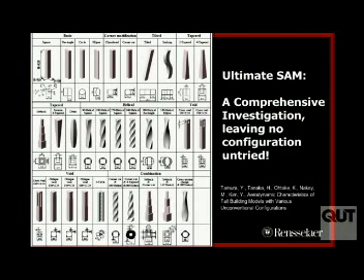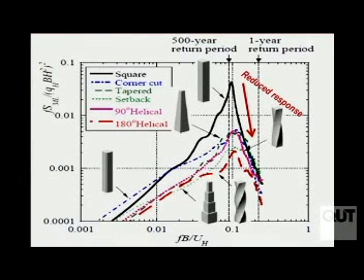I have colleagues and this information is available on the internet. If you go to Tokyo Polytechnic University, they have a fabulous facility for you to check the aerodynamic performance of a particular shape of a building. They've got all this data in a database, a very easy to use, if you like, interface to look at the crosswind response of a structure for various shapes, and they've done all of these different types. And again, you can see clearly, again, a reduction. The response is the vertical axis and the horizontal axis is basically frequency. You can see that these sorts of things playing with the shape, the profile of the structure, reduces the response.